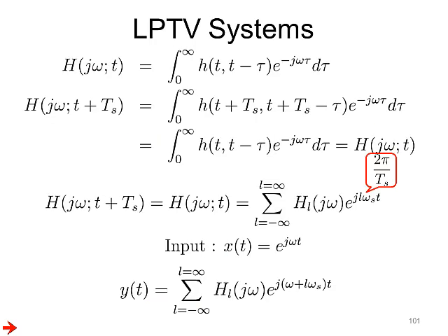Now, the time-dependent frequency response of a linear, periodically time-varying system is basically, in simplistic terms, the gain experienced by a complex exponential as a function of time. If the properties of the network are varying periodically with time, it makes sense that the gain experienced by the complex sinusoid also varies periodically with time. Therefore, the time-dependent frequency response has a period of Ts.